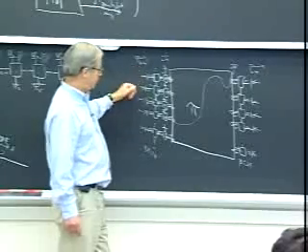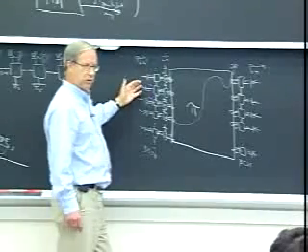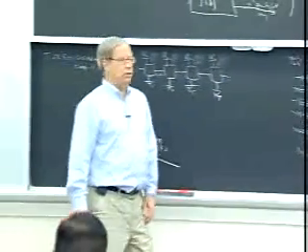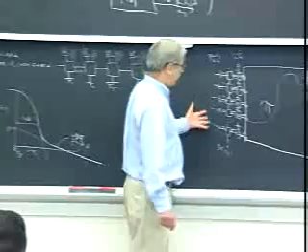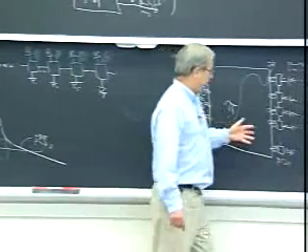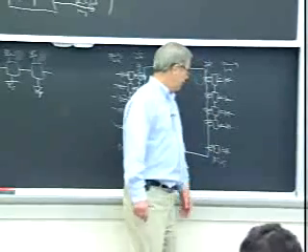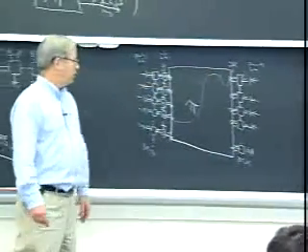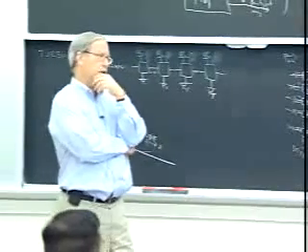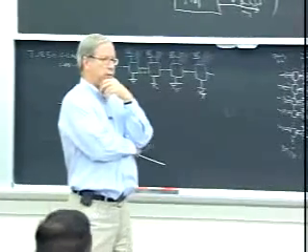But then of course it makes decoding harder because you don't get any received information from the bits that you don't send. That's called puncturing, and there are various philosophies of it that I'm certainly no expert on. And it's possible that by being very clever about puncturing, you could do something about minimum distance.